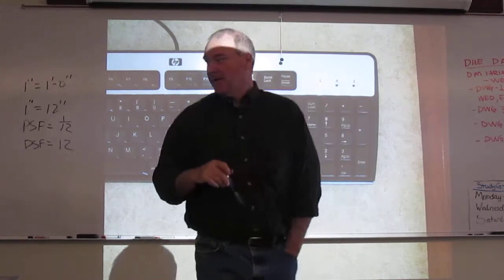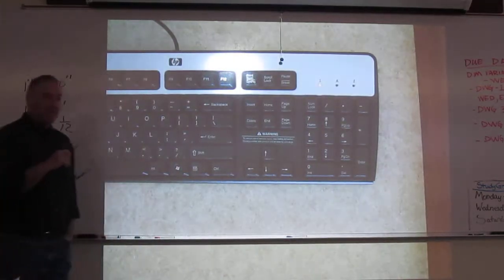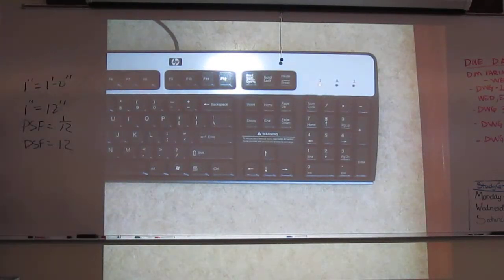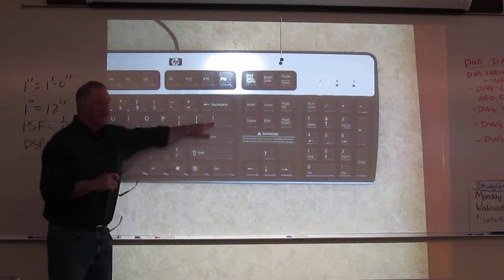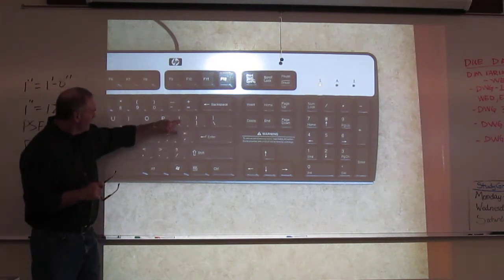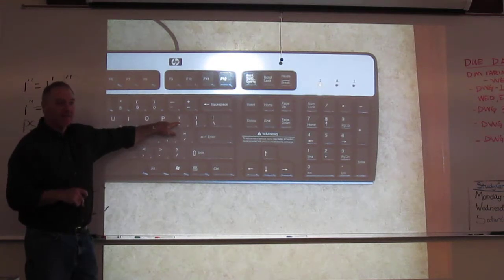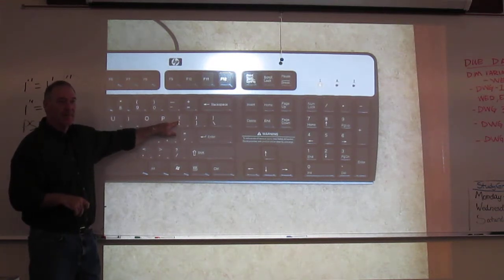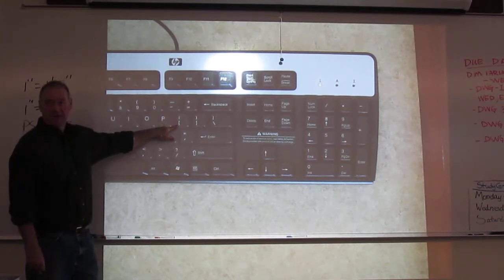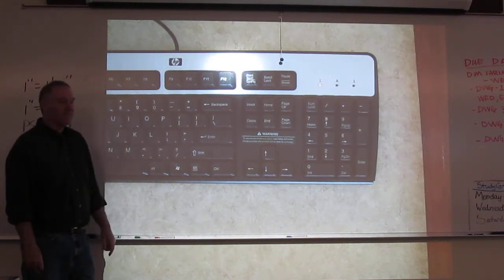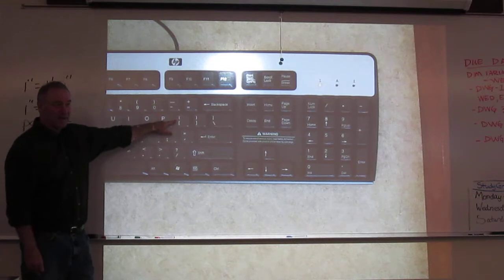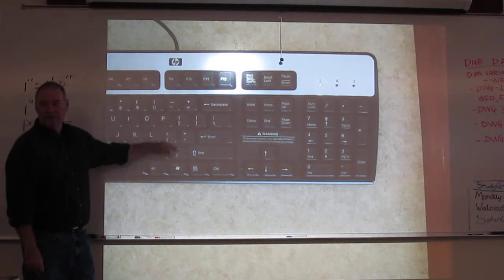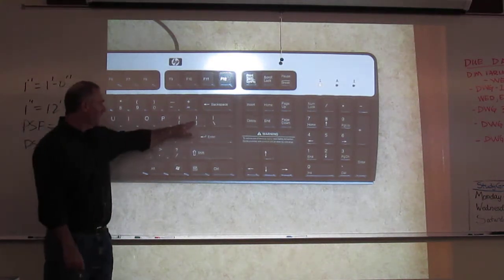Gotcha. All right, now you have some keys on your keyboard that are going to have some nice things for you. Namely, these guys right through here. Okay. Punch this first bracket key. What pops up on your screen? A bracket. Okay. If you see a bracket, you're not in artstyle.shx. Hold the shift key down and hit the same bracket key. Sweet. Okay, do the next one.